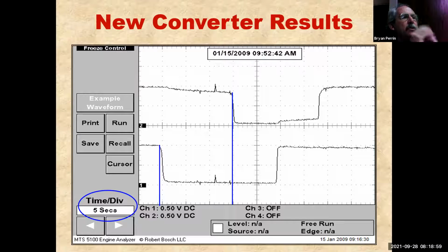So we're going to manipulate the fuel. And the nice thing about this is it completely takes fuel trim out of it because I'm not reliant on my vehicle's fuel control to test the catalytic converter. Because now I'm in charge of that fuel control. I'm the one taking away propane and removing propane. If I'm doing any of the tests we've talked about previously that were the tests that don't work so good, or if we do a switch ratio test, I'm dependent on what? Fuel trim, because we know fuel trim switches the O2 sensor. So if I have a problem with the O2 sensor, problem with the fuel trim, it skews the results. The magic of the OSC test is that I'm removing that.